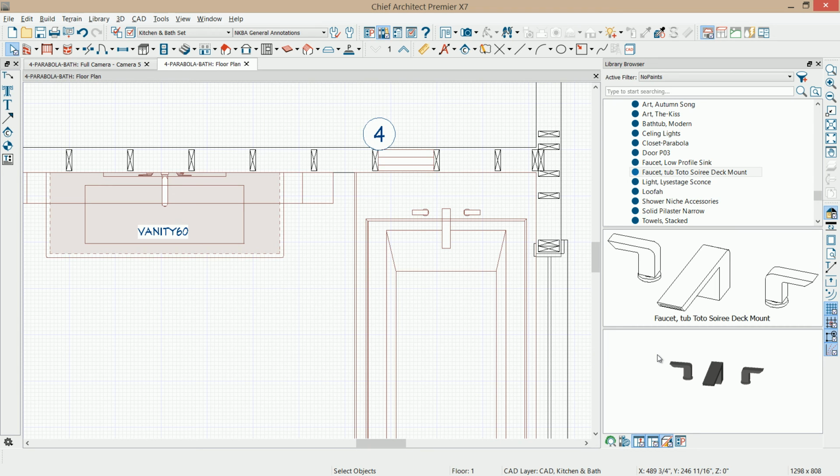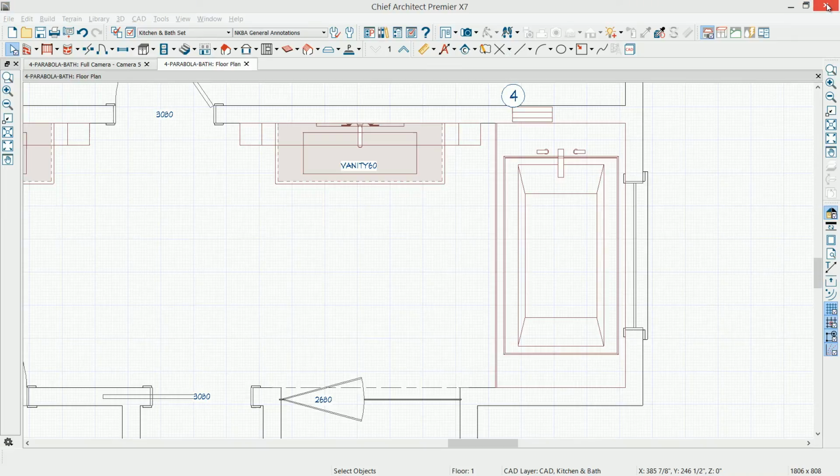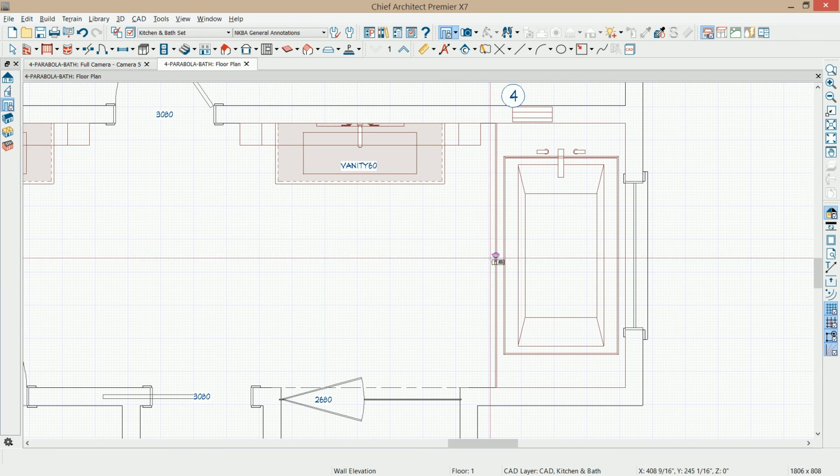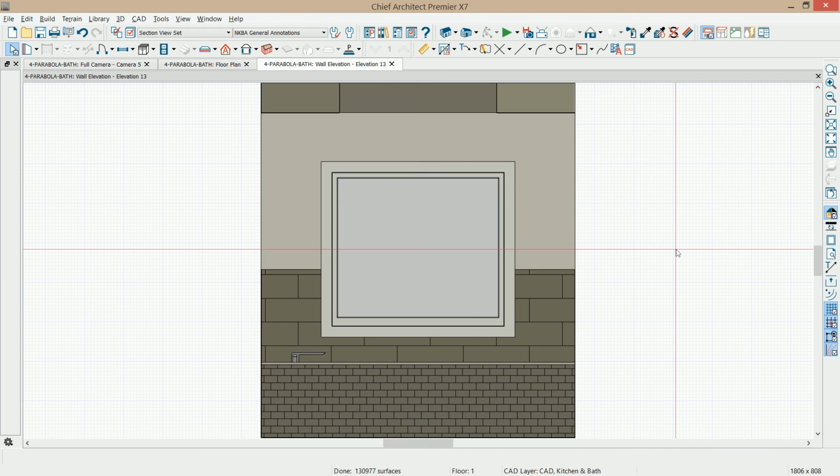And with my floor plan notes, I'm going to put on the plan in a subsequent video for the construction drawings. I'll be able to refer to that access panel and that footnote for the tub. Now the final step for the tub platform is to create our niche that surrounds the back wall. And I'm going to use the same process that I did for the vanity if you were watching earlier. In the wall elevation, we'll use the Backsplash tool here.